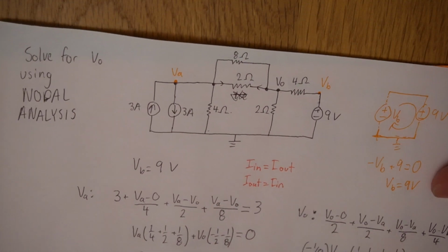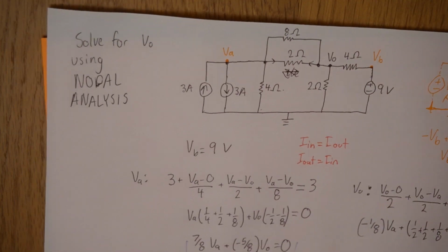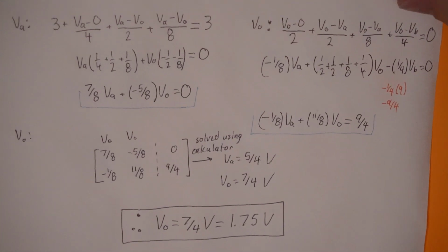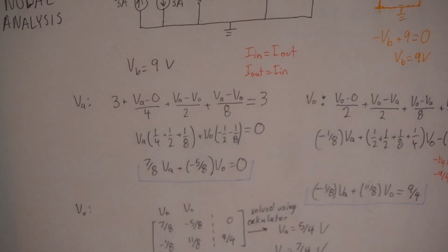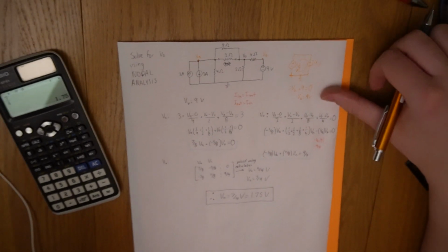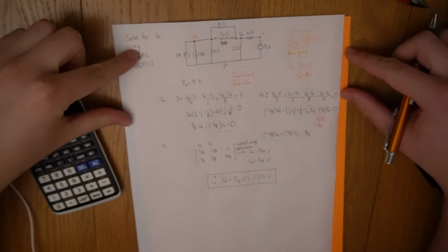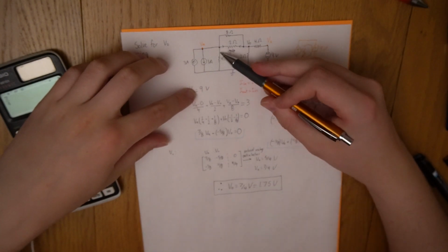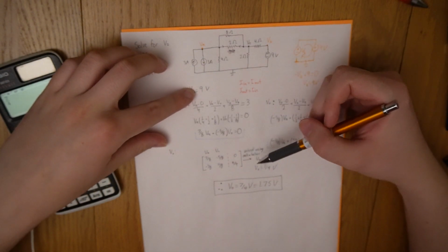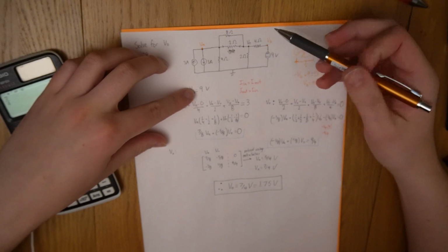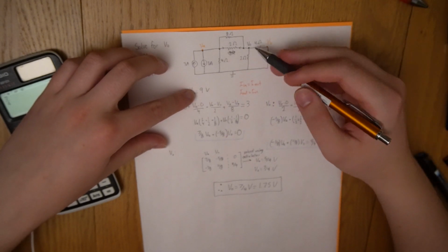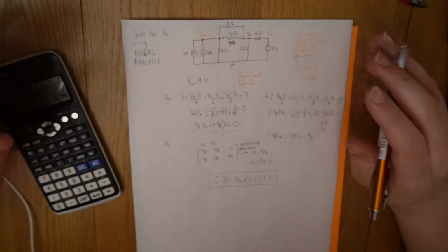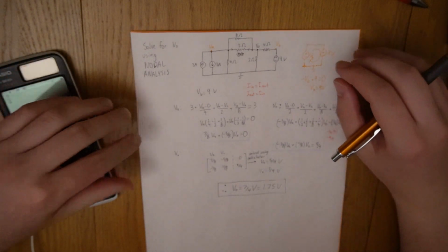A simple nodal analysis problem. I'll just run it through by camera in its entirety. I'm going to zoom it out. And there you go. Now, how we can make this more difficult is by adding dependent sources, which would just mean we have another equation to solve for. Or we can add supernodes. If I had stuff in the centers, it'd make things difficult. I'm not going to solve supernodes or super meshes right now.